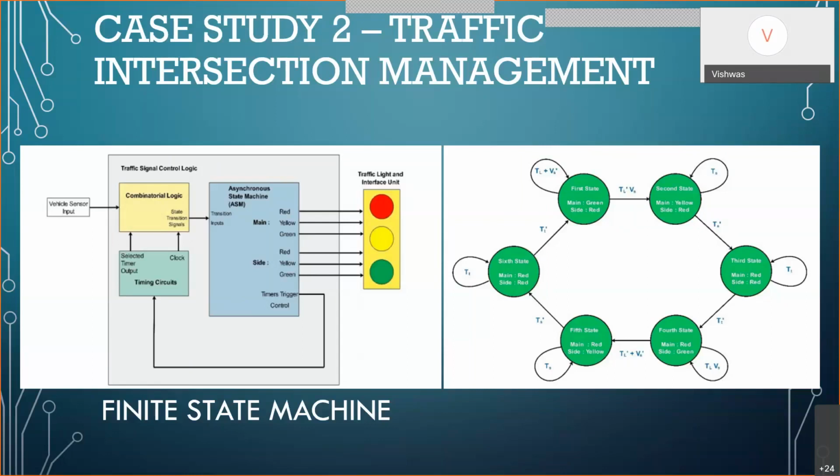So once you power off and power on, the whole configuration goes off, and you can directly start a whole new configuration. So an FPGA will help you in smaller scale products, like network products where the cost of the product will be in crores and you'll be selling only a few thousand of them. Then you will definitely go for an FPGA rather than an ASIC. So that's the difference between FPGA and ASIC in terms of requirement and purpose. So that is about this finite state machine and this thing.